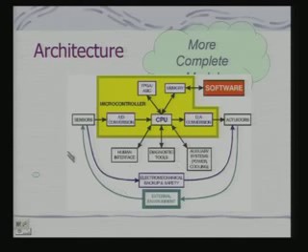Now, let us look at other issues. One is obviously on the CPU, we need to implement with the CPU the human interface. If you are talking about any kind of reading to be obtained through the embedded systems, any control function to be altered by the human users, I need a human interface. So, this interface becomes an important component. So, you will find in many cases you have an LCD display panel or a simple LED based informative color codes by which the user can be informed of what is happening inside.